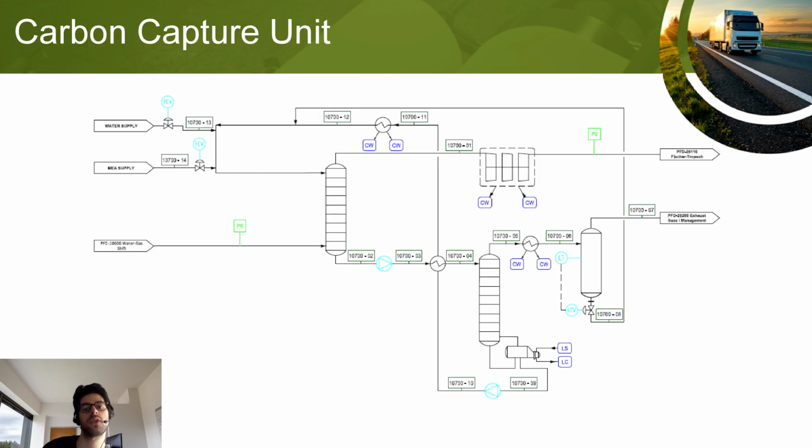A carbon capture unit should have been implemented before the Fischer-Tropsch reactor. However, undesirable molecules would be driven through the reactor, such as ammonia, which would greatly harm its reactivity. So we decided to put this unit in a recycle loop instead, after the Fischer-Tropsch reactor, heading back to the bark gasifier to break or capture the unwanted molecules